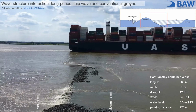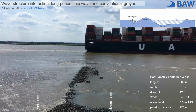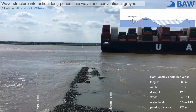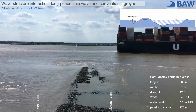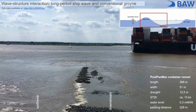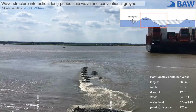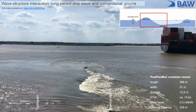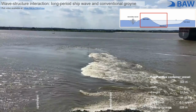We can now see the upstream groyne field beginning to refill with water as we anticipate the arrival of the stern wave. Due to focusing effects, wave energy is highest in the root area. The arrival of the stern wave, working with the drawdown-induced water level gradient, sets up a quasi-stationary, highly turbulent overflow over the groyne, as we can see here. This overflow process begins in the root area and spreads along the groyne body. It is precisely these overflow events that can be highly damaging to the groynes.